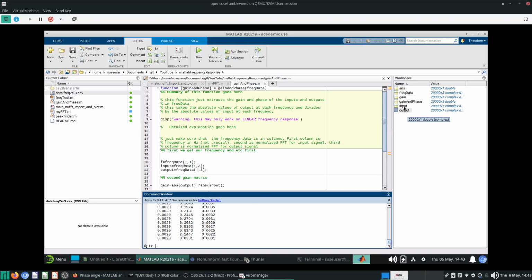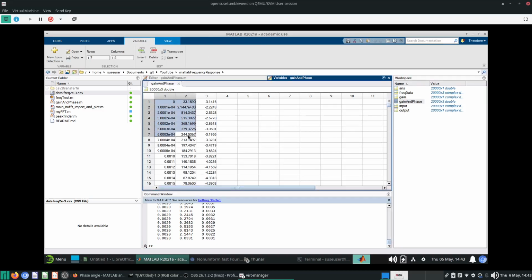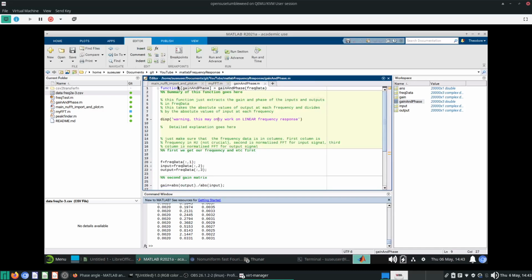This one will tell you what all the various gains and phases are at each frequency. The frequency we are more concerned with is of course based on our input frequency, which should be 2 times 10 to the minus 3, which is here. You can see the gain is almost close to unity gain, and the phase angle shift is about minus 0.356 radians. So that's all there is to this gain and phase.